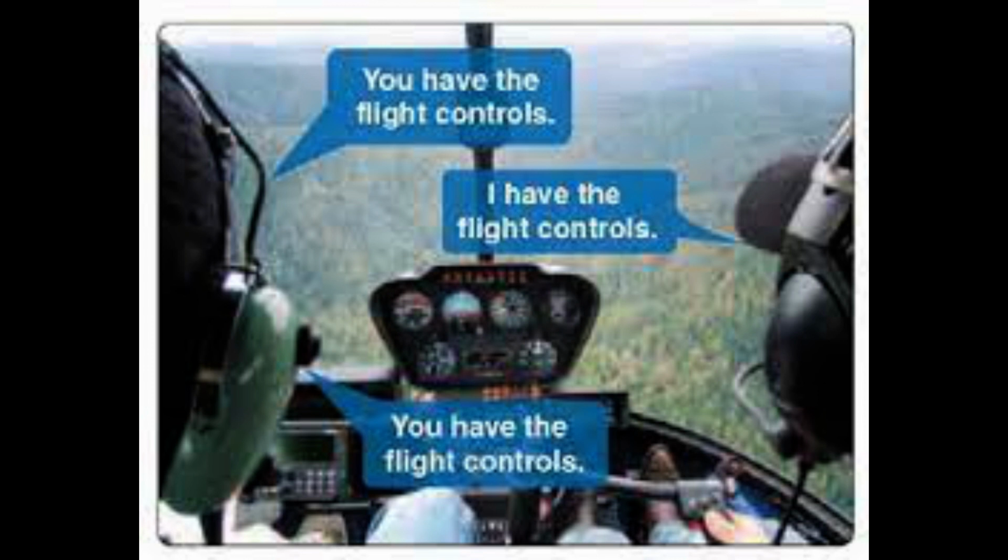When engaging the autopilot, it is a good idea to announce that the autopilot is being engaged, what autopilot mode is being used, and then to confirm the settings using the flight mode annunciator. It has been general practice for many years in many aircraft to first engage the FD to determine what instructions it was going to transmit to the autopilot.